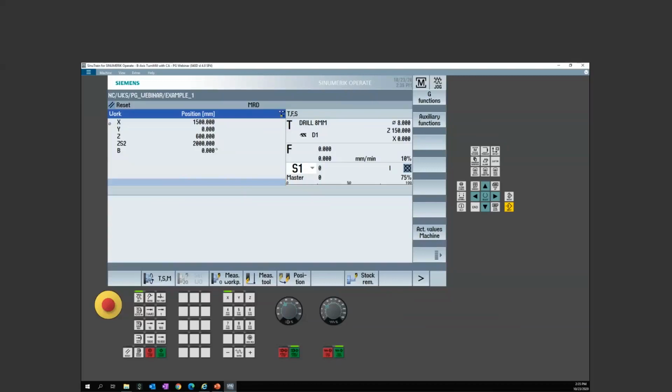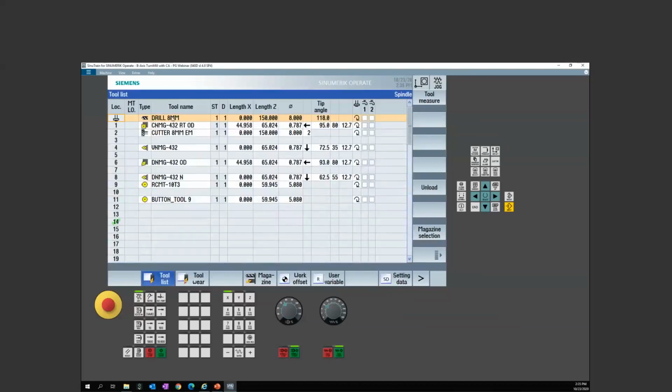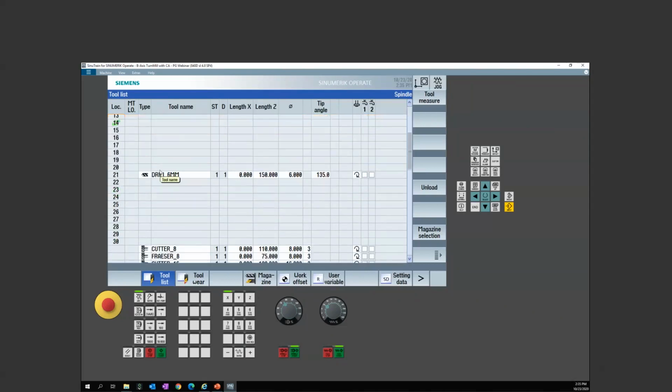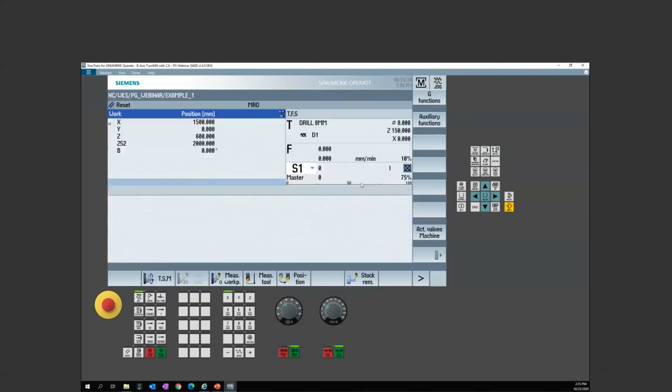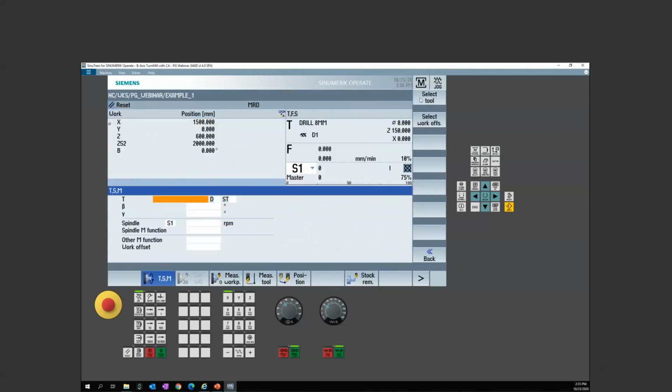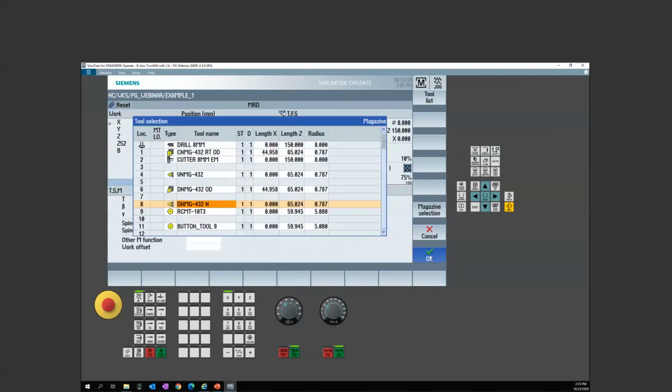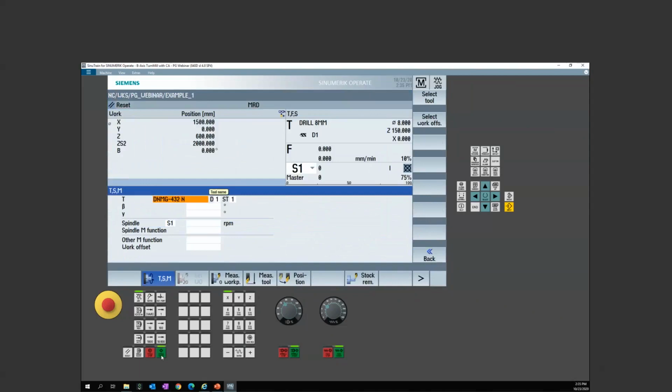So we were talking about different tools, right? First things first, maybe I'm using a standard, we'll do, where's my DNMG neutral tool? So I'm going to do a quick tool change, do it through TSM. I'm going to do a quick tool change to that tool. So at B0, you see how my cutter orientation was set up in that position 7 like we just showed.